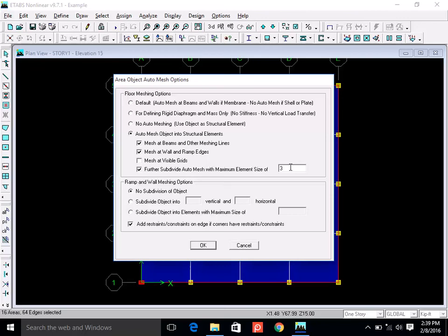So if I make my mesh size 1 feet, then in 15 feet I will have 15 meshes, means 16 connection points, right? So more number of meshes, or I should say smaller mesh size, results in a better quality analysis because you become more close to reality. But after a certain mesh size, if you keep on increasing the number of meshes, the results are not changed much. So it's like optimum moisture content, you remember? And that also is burden on your memory.